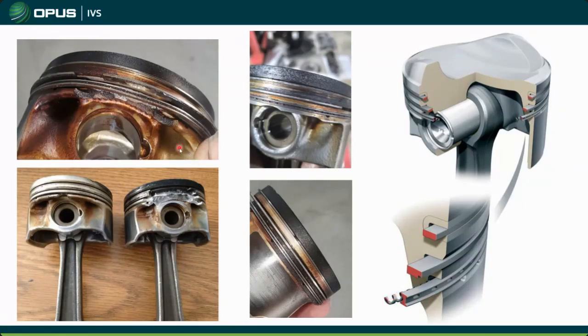As you can see in some of these pictures, this is what would happen. You can see the oil and the carbon just starts to cake inside of this. Here's one that's not terrible, so you can still see the oil passages here. But look at some of these other ones. They just get all clogged up, and this leads, of course, to low compression and heavy oil consumption. Really bad stuff. Now, what can you do about this? At the dealership, we would run an oil consumption test where basically we would measure how much oil was in the engine.